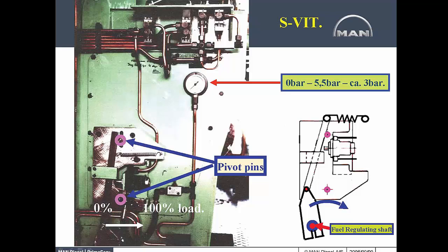Now, when you look at this screen, what you are seeing both in a photo and over to the right on a diagram is how this pneumatic signal is changed as the governor changes position, and how you set that lower break point and the upper break point. And it's done mechanically. Now, what you're seeing is you have a little pneumatic air regulator, and it has a pin that sticks out from the front of it. And then you have a bar that goes up vertically. You've got this bar, and you've got a spring pulling it to the right.